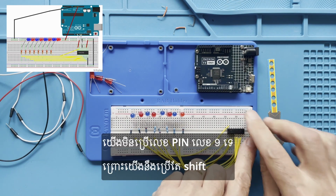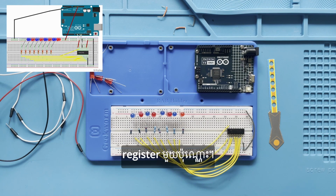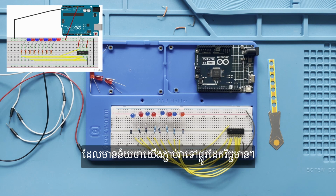We don't use pin number 9 as we will only be using one shift register. We don't want to reset the shift register, so pin number 10 has to be set to high, which means that we connect it to the positive rail.